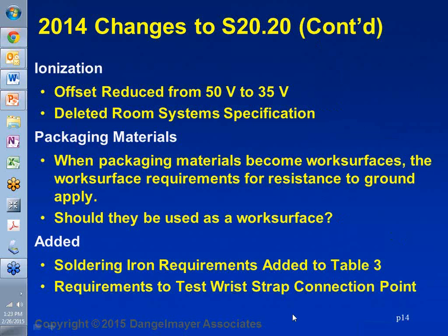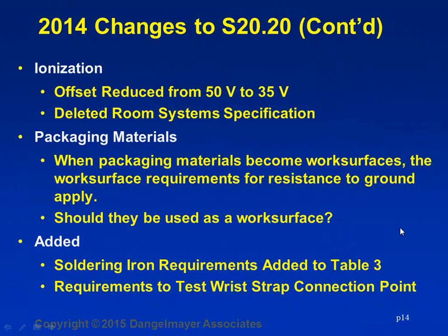One question that came up regarding the flooring footwear, I noticed. I'm not sure Ginger covers this part of it, but if you currently have a floor installed, do you have to get it done? That is a kind of nebulous area, because there is a grandfathering clause in 2020 that allows you to use your existing compliance verification data for your flooring footwear system. From a best practices standpoint, I would start collecting body voltage data at various times of the year to account for the difference in humidities that might occur in your process. Just start collecting that data, along with resistance data, to show an auditor or an assessor, and satisfy yourself that your flooring footwear system is working the way you want it to.